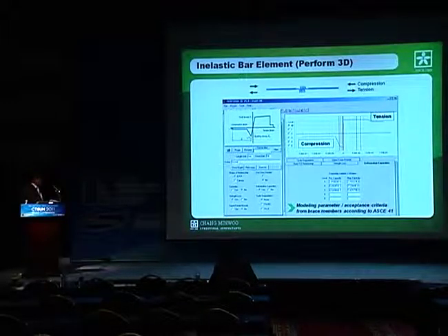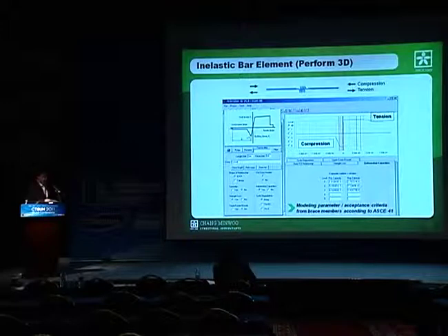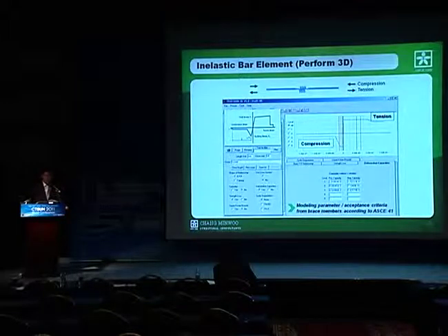This slide shows inelastic bar element properties. This model can reflect axial behavior, and in compression, it can show the buckling strength calculated using the Euler equation. The modeling parameters and acceptance criteria for deformation were evaluated using the ASCE 41-06.